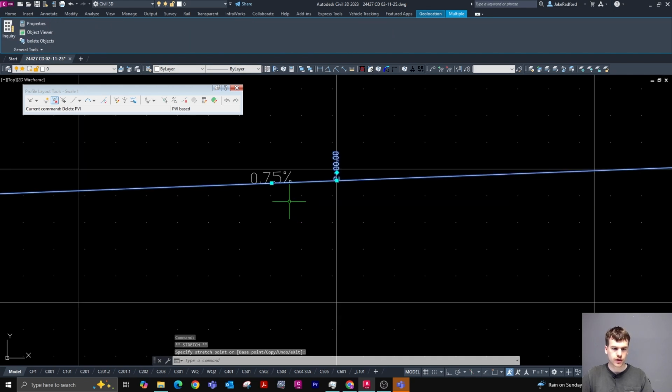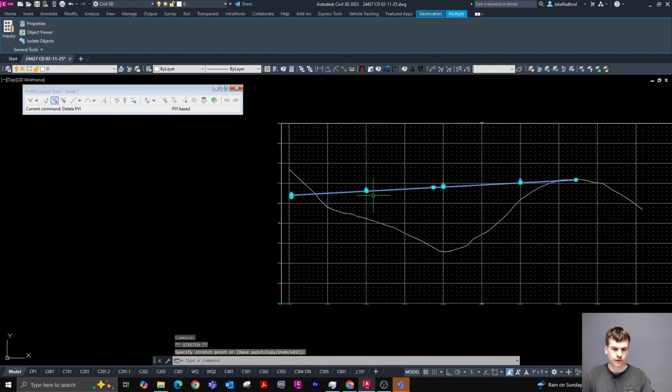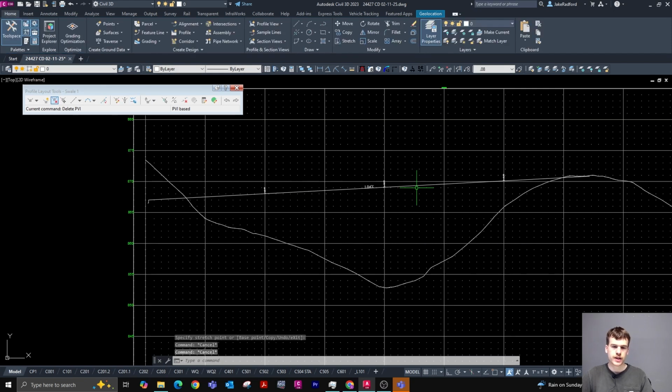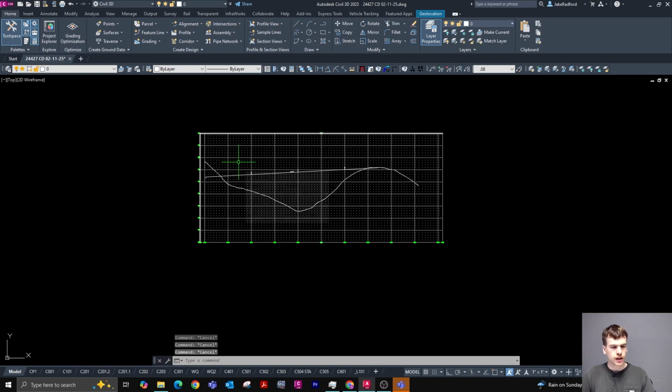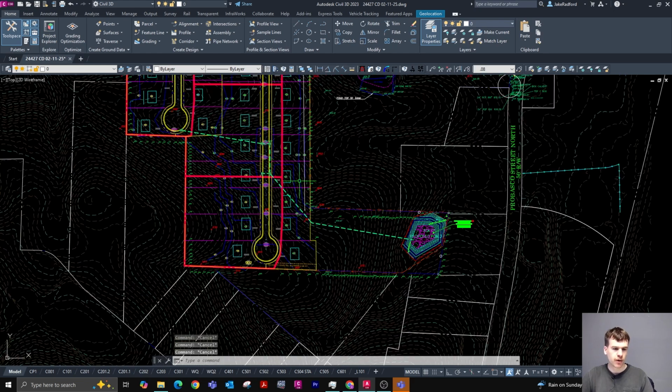1% slope. So I'll go ahead and drop that bottom end a little bit more. Now we're at 0.75%. We'll drop it another foot. Now we're right at 1%. So here is our swale here, the vertical profile that our swale is going to follow. So we can close out of these profile geometry editor tools, and we can go back to our plan view.